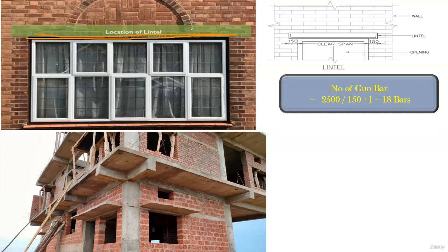Of course, this is a cut lintel. This is a full lintel. If it is a full lintel, you have to take the complete length. If it is a cut lintel, only in this portion your chajja will come. Okay. If you haven't seen that, then I'll show you one image for that.